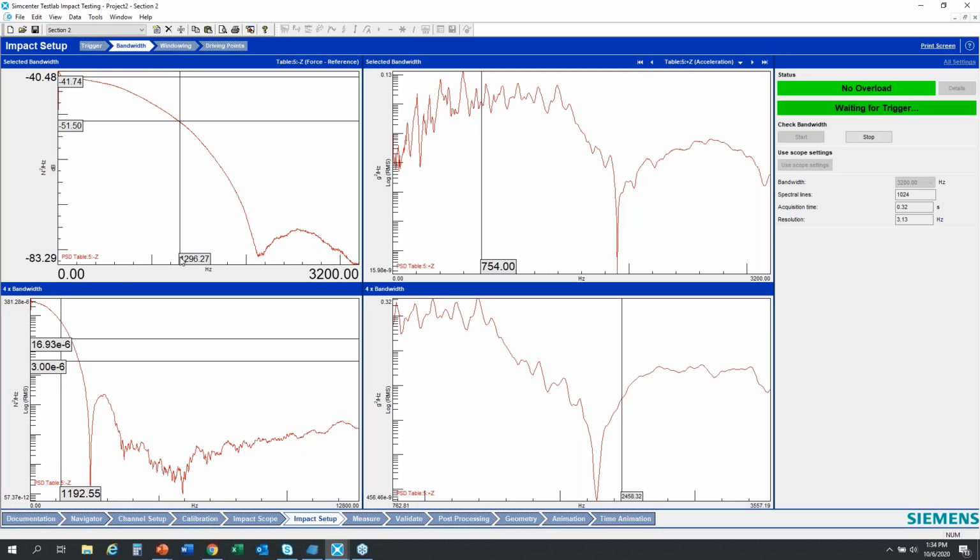All right. So what we're looking at here is the force input. And one of the nice things about the hammer is it's a brief transient event, a good click, so to speak. And transient events, when we perform an FFT, give us a nice broad frequency response. So when I hit something with this impact hammer, one of the reasons it's used as this tool is I'll get a nice flat force input over a given frequency range. Now it's not perfect, that force dissipates or rolls off over that frequency range, and that's what we're looking at here. So this is my force roll off.